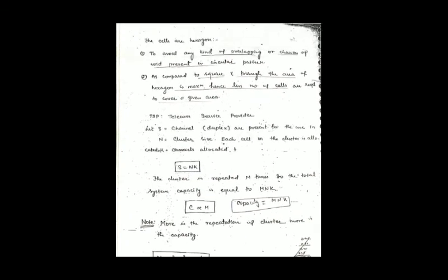There are two reasons why we choose the hexagonal cell. We could choose circular or rectangular, so why hexagonal? There is a logic behind this. Point number 1: to avoid any overlapping of the cluster or to avoid creating any void in the circular pattern. Just see here. Suppose there is a circular shape, you start drawing one circle, two circles. When the circles meet, there will be some void present in the center.